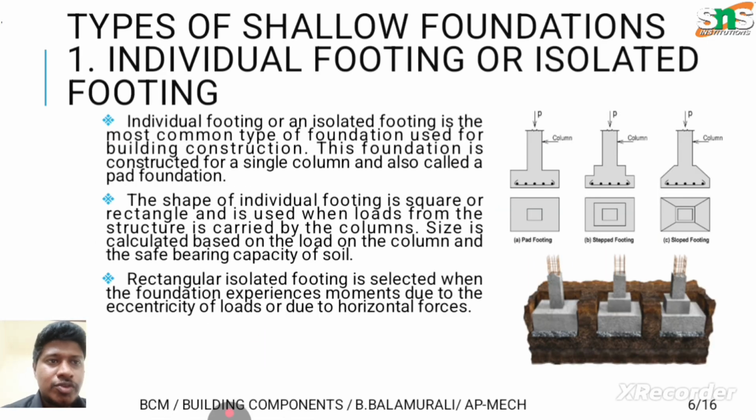The first is individual footing or isolated footing. In the image on the right side, you can see that each column is separately connected with the soil, not both columns together. So it is called individual footing or isolated footing. It is the most common type of foundation used in building construction, constructed for a single column, and also called a pad foundation. A rectangular isolated footing is selected when the foundation experiences moments due to eccentricity of loads or due to horizontal forces.